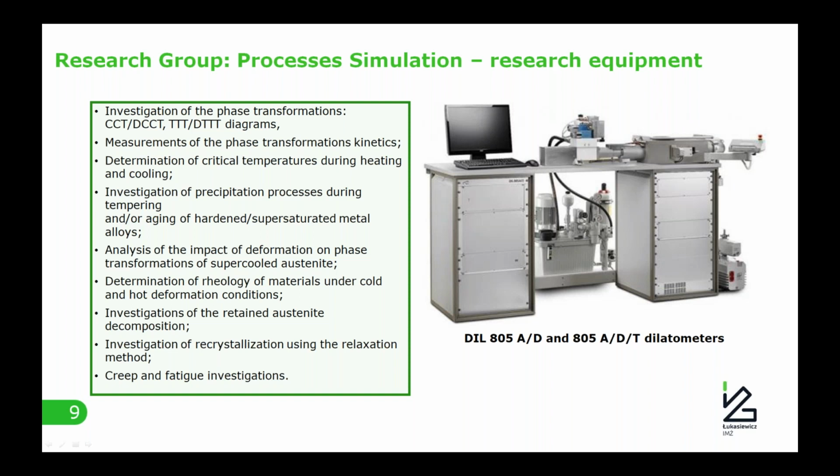Generally, the dilatometer allows for the investigation of phase transformations of non-deformed and deformed samples in the course of full sample compressing and round and flat sample stretching, investigation of sheet metal. Apart from the linear variable differential transformer system, the dilatometer is equipped with an optical contactless system for measuring diameter changes in the sample during a programmed thermal cycle. This system allows for independent temperature measurements in 3 points of the sample. The dilatometer's control system allows for the conduction of thermal and thermomechanical cycles as well as short-term creep tests.